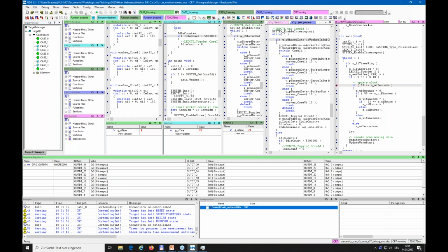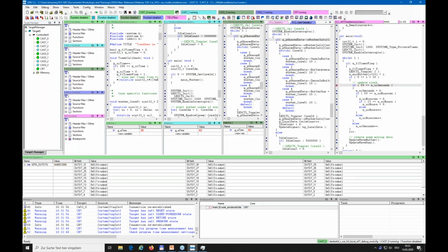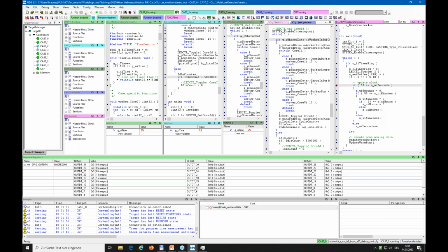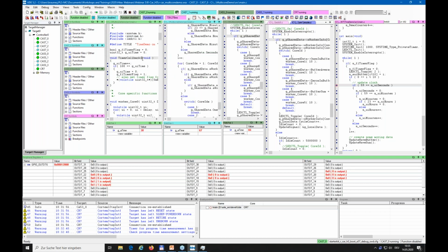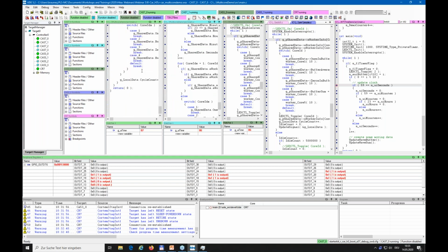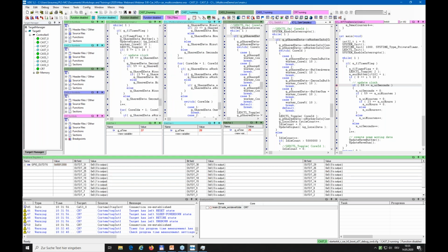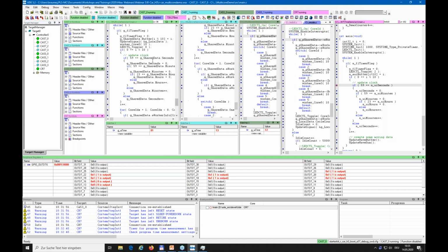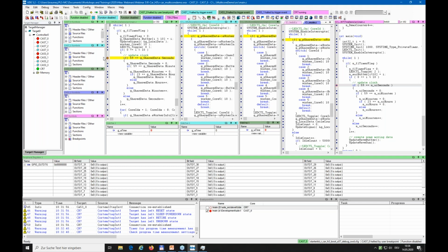Start this. And then if I set a breakpoint, for example, in one of the Cortex-A cores here, let me look for a good, we have also a clock here, and we can set a breakpoint also on this line. And you see we hit the breakpoint here, and at the very moment, all the A cores are stopped synchronously. Here you can see that the R7 is running, still running.